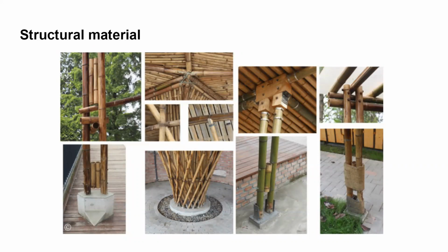Therefore, these are the main materials in this pavilion. First is bamboo, because its property has the toughness to resist tension as well as the ability to resist compression like timber. Also, it is an experimental material to explore a new method of temporary handmade construction based on the traditional method of bamboo techniques. Also, bamboo is human friendly and gives back-to-nature feelings. Also, bamboo grows fast, is hard, and is easy to process and reforest. The second is steel for the brackets, with high tension resistance. Third is rope for the ability to resist tension, and the last is wood.